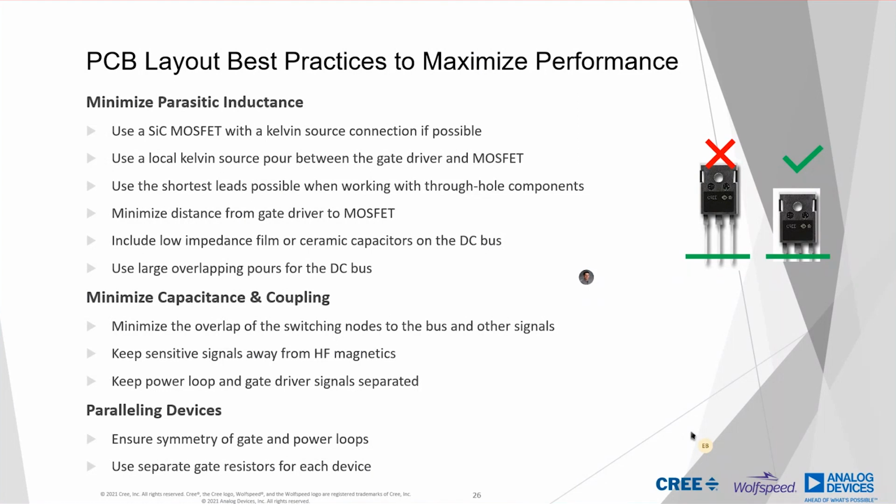And then keeping separation between the power loop and the gate driver loop. You don't want to be running high power traces underneath the gate driver, again, because it can pick up interference and cause undesired operation. So try to separate a power side of the board and a control side of the board. And then we didn't focus on paralleling in this presentation, but the high level takeaway there at paralleling is symmetry,